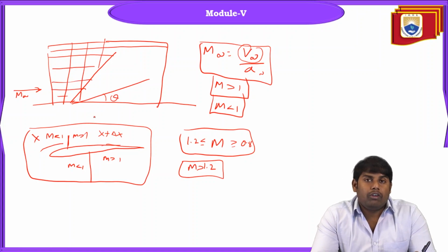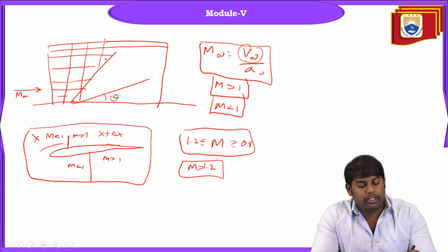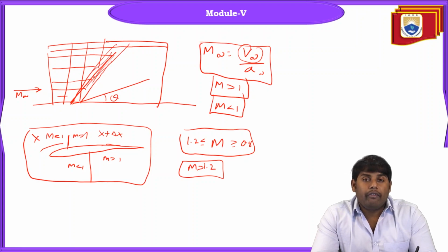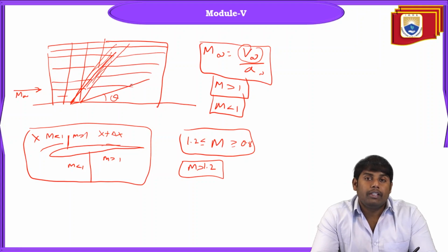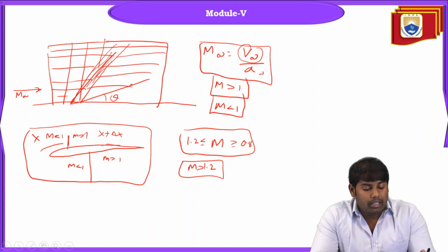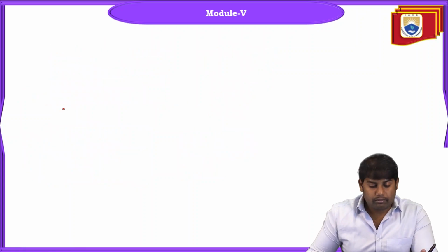So here, what is happening? We need to mesh the shock. Let's say this is the thin layer. So this is a very thin layer. So you need to precisely space the grid points in such a way that you capture the shock. Okay, so this is one technique, and the other technique we have is fitting.